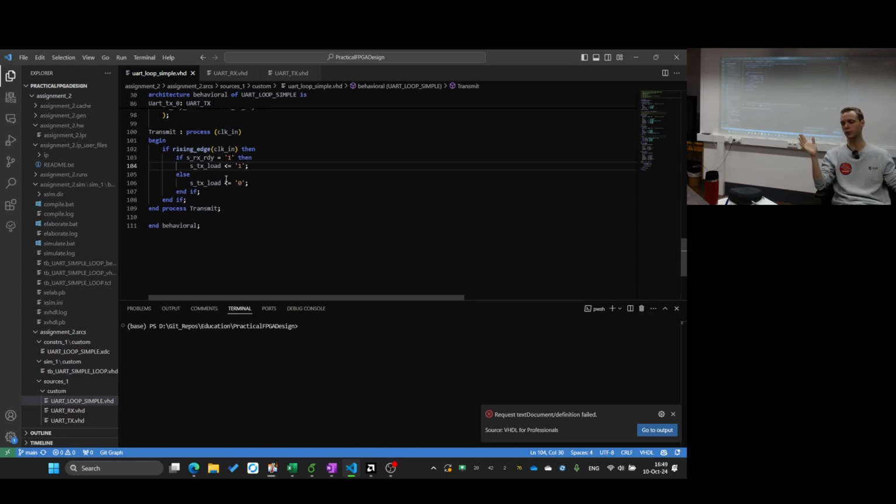You may not have to assign to every signal, because throughout the process you will only assign the signal when you think your design through after 5 clock cycles. I don't need it before that, so I will not read it before, so I don't have to reset or assign a value, because it will automatically eventually get a value. We will come to that in timing stuff and the optimizations of design. Just so you know, in general there's always a reset, but you may not need it for everything because it will automatically be assigned.